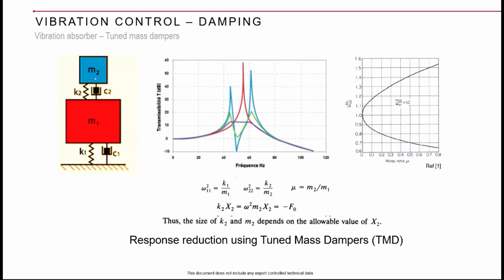you design an additional secondary mass which splits this. I mean, this acts in the opposing direction as an inertia, and because overall this becomes a 2 degrees of freedom model now, there will be two different modes instead of one single mode. The design criterion is the ratio of the second frequency to the first frequency as 1. Now, for example, if you choose a mass ratio of 0.2, then you will have two modes at 0.8 and 1.25 or around like that. Okay, so this will be at 0.8 and 1.25.